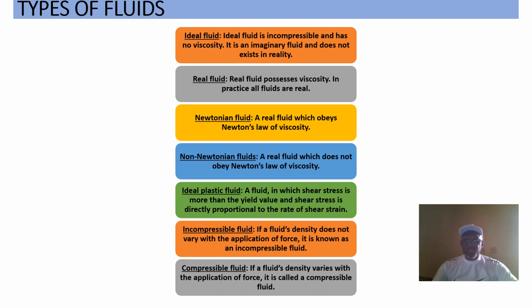Types of fluid. We can generally classify fluids as ideal fluids. Of course, when we talk about ideal, we're looking at an ideal situation. So we say an ideal fluid is incompressible and has no viscosity. It is an imaginary fluid and does not exist, you see. So it is an ideal situation. Real fluids possess viscosity, and in practice, all fluids are real.